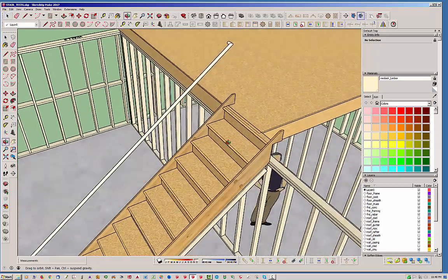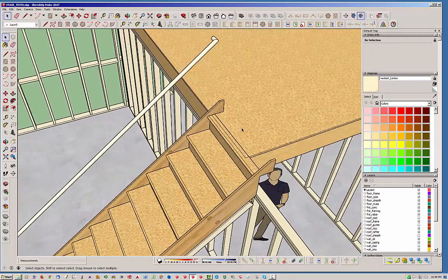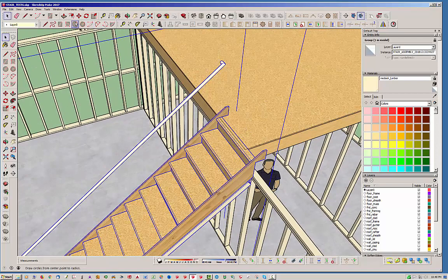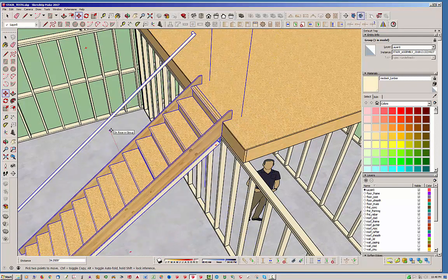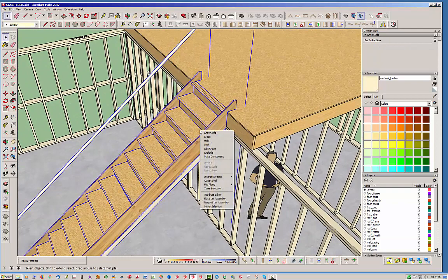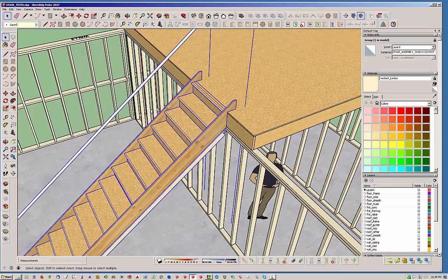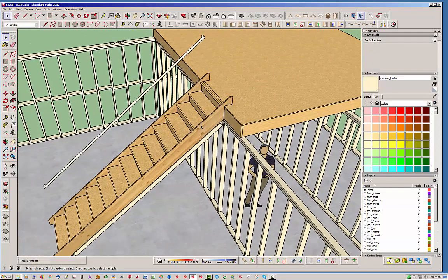Okay, close that out. Now, mind you, you can move these. If you need to shift this over wherever you want it, you can always move these assemblies and manually move them anywhere you like. And then when you regen that assembly, it will regen or edit in exactly the same spot. So it's not going to go back to the origin or something, which is kind of nice.